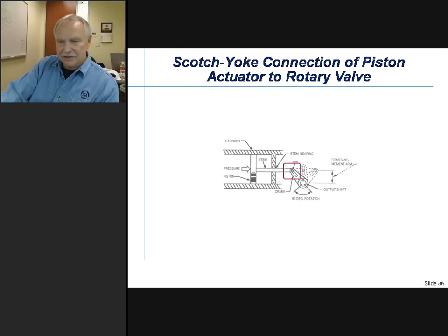The piping valves, gosh, they did great as piping valves, as isolation valves. But that usually means they don't make good throttling valves. And so spending the extra money to go to a control valve manufacturer and get a real throttling valve was something that was often not done on projects in an attempt to save money.